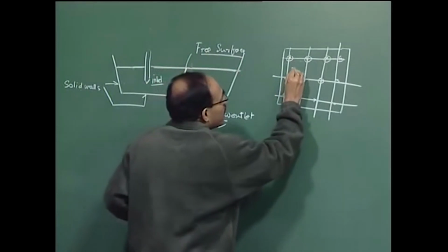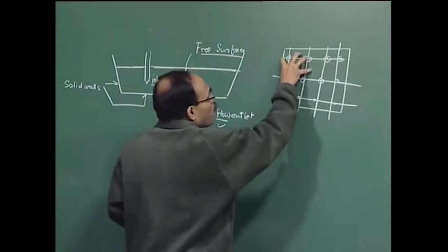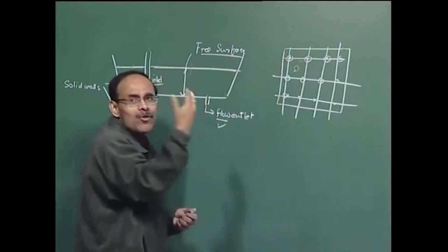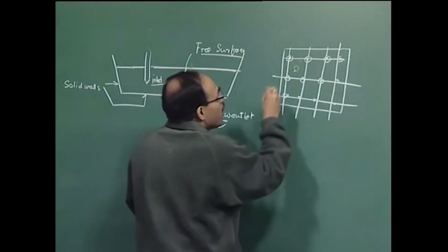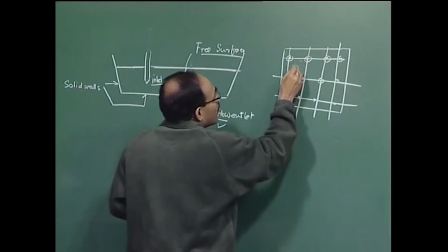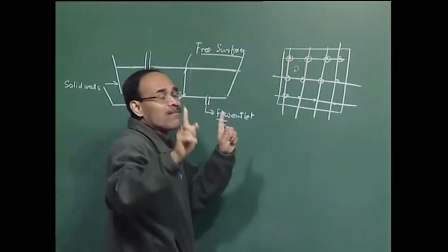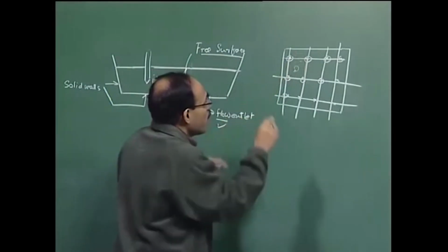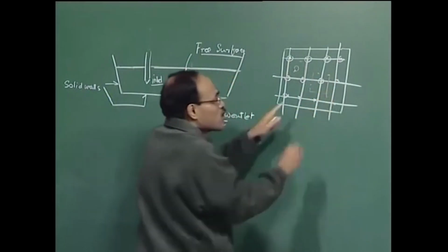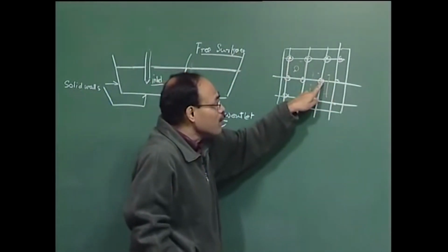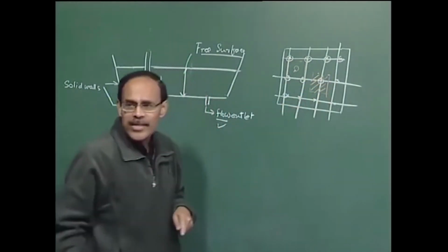Now if I have an eddying motion here, and the control volume is this big, I will not be able to see whether there is a gradient of velocity here or not, because in this particular control volume, it is a very big control volume and it has a characteristic velocity. To be specific, every nodal point here is associated with a control volume, and the value of Vx is assumed to prevail generally over the entire control volume.